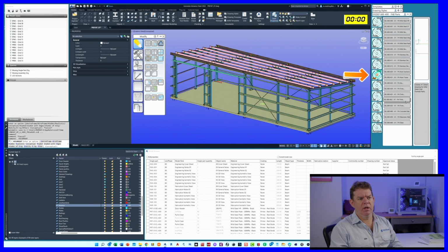Then we're into our fabricating single part processes, which we've split up into different groups so that it basically groups different types of single part material processing. So we've broken it up into the hot rolled elements for mild steel, and mild steel cold formed elements. So these are your hollow sections, so your RHS, your CHS, your SHS, those types of elements.